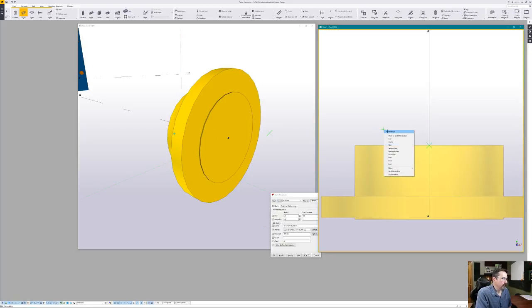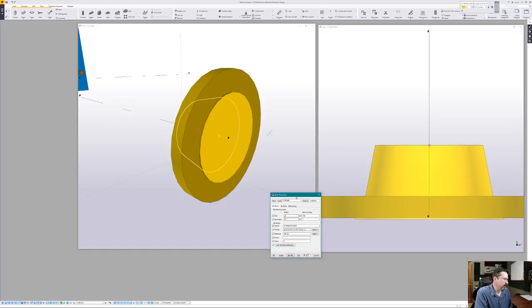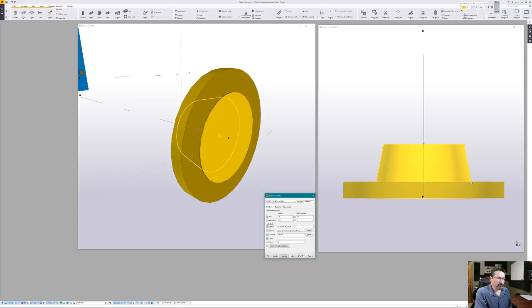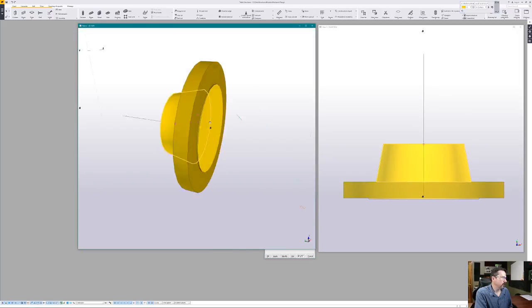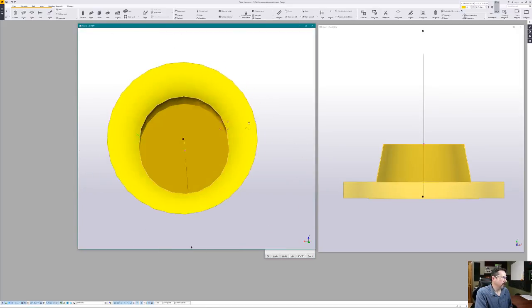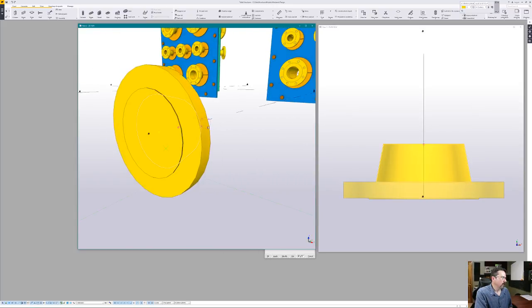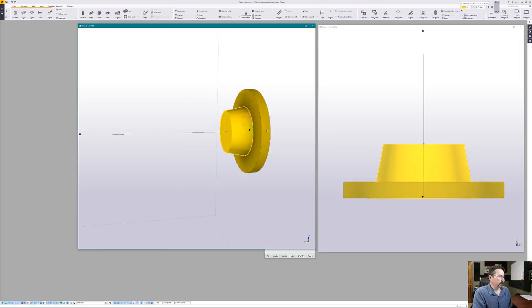And that didn't show up there, because I didn't hit the apply. So there, that is the part that we just put on there. It starts off at the 5.31 inches at the large end and tapers down to 4.5 inches. So here we have the basic shape of our flange, of our Class 150 raised face weld neck flange.